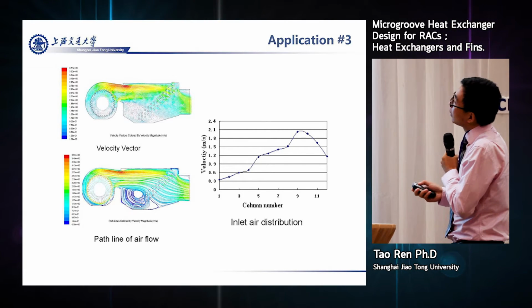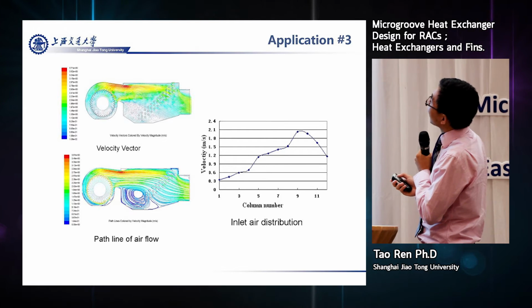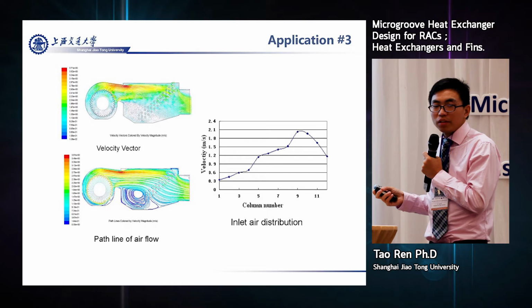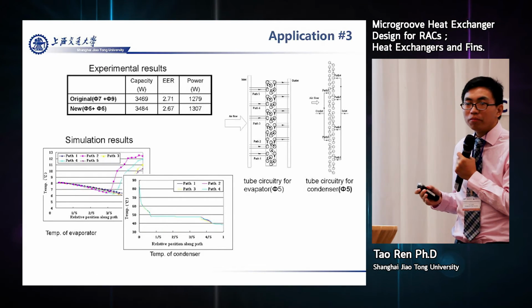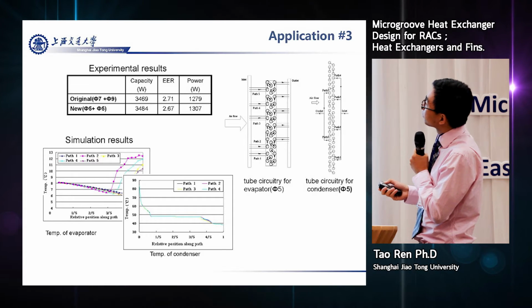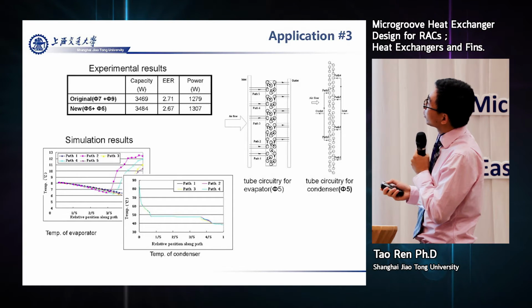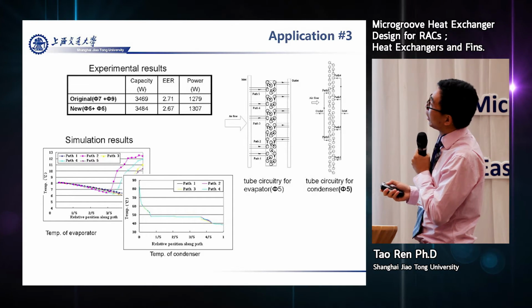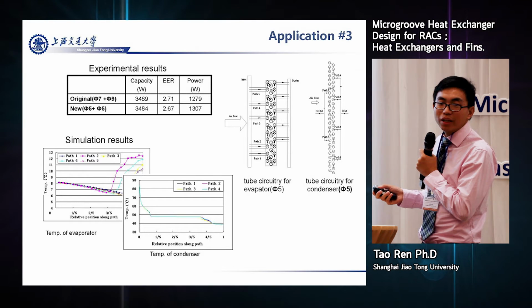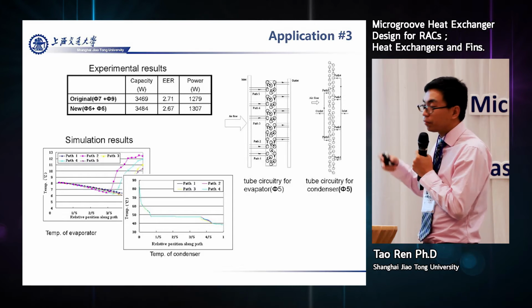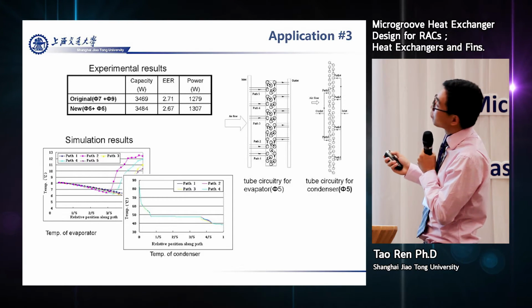We can see that for this case, as the flow paths increase to 5, it's harder to deal with the circuitries, because it's very hard for us to make the vaporization point the same, or at the same relative length, in the heat exchanger, because the total heat exchanger has become more complicated.